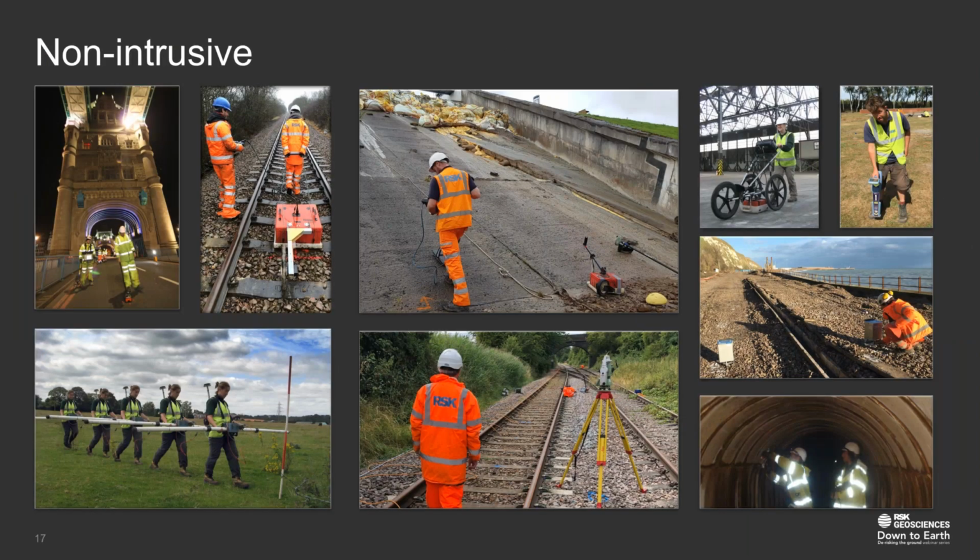There are a few non-intrusive methods that we can consider when planning our investigations, including geophysical methods and photogrammetry. The majority of the work is generally in the upper 20 meters of the ground, but typically for our sites and our ground conditions, it's going to be in the top 2 to 5 meters that these investigation techniques are going to help you. Geophysics includes techniques like seismic refraction, electrical resistivity, and ground penetrating radar to gather subsurface data without breaking the ground.